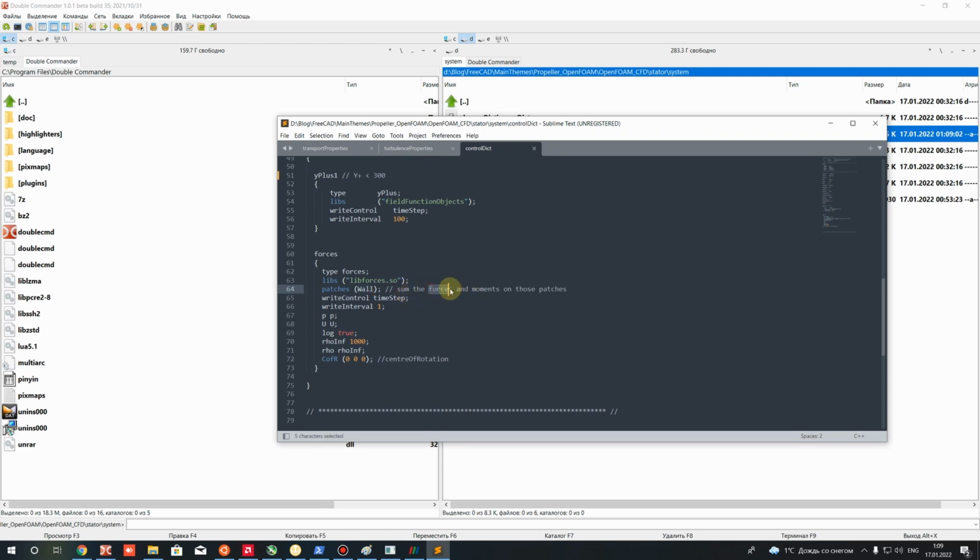It means if you divide it by the gravity constant, you will get the thrust. I will press here the force divided by g. The force is z, because our rotation axis is z. Here we have to divide by g, the gravity constant. You will get the thrust in kilograms.